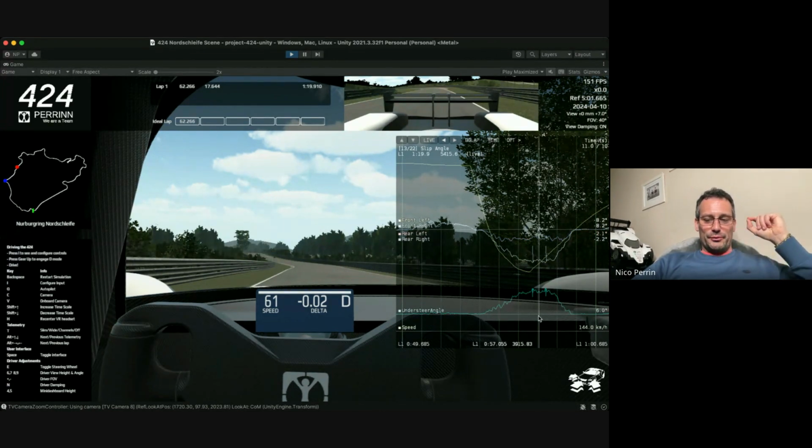It's a little bit too much. I would like to have less. You always have some understeer in the car because it would be nearly impossible to drive a car that always oversteers. But I think we have a bit too much understeer in 424, and it's something we've been working on, and we still have more work to do. One aspect is a feature of the simulation as well: in a simulator, the driver tends to put more steer angle because we are not modeling the temperature on the tire and the thermal effects, so you cannot overheat the tire, and it sometimes gives you a bit more grip. So I have to remind our driver to not put too much steer angle. Okay, so that's the understeer channel.